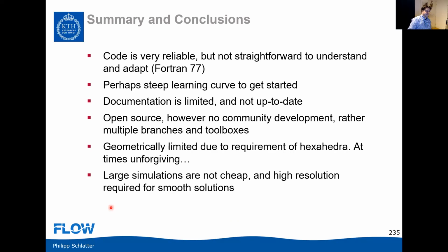There are perhaps also a few, well, drawbacks is maybe the wrong word, but I would just like to say that perhaps the documentation is still somewhat limited, and there is a certain steep learning curve when you want to start with NEC5000. It's not only a steep learning curve when it comes to documentation, but also the numerics is perhaps at times a little bit unforgiving, which is good and bad. Sometimes your solution blows up and you may not directly know why this is the case.